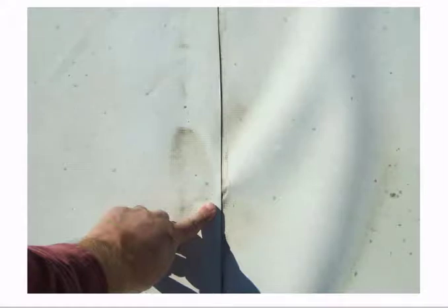Craig, what are we seeing in this photo? So this photo is what we call a reverse fish mouth. It's a wrinkle in the bottom layer of the membrane. The bottom field sheet may not have been pulled down tight, or there was a wrinkle there due to fastening. But a trained eye would think that's good, it's not going to leak because we got three quarters of that weld done.